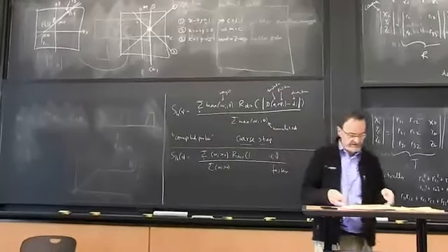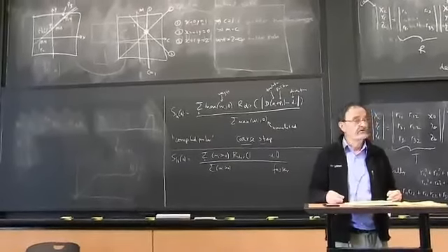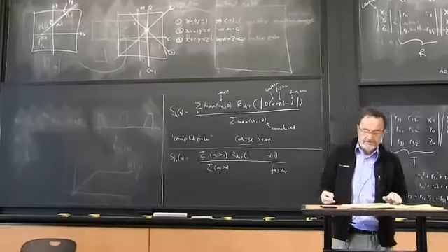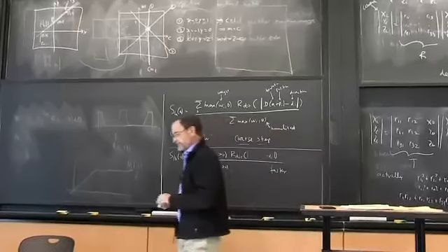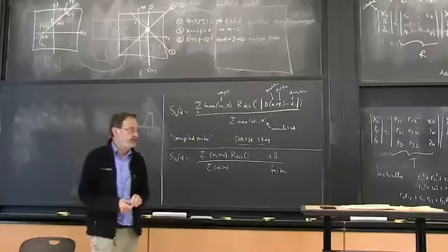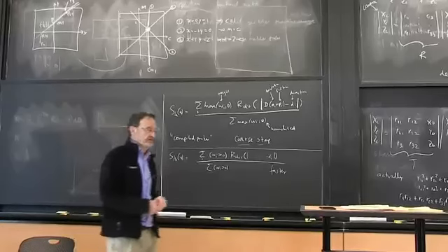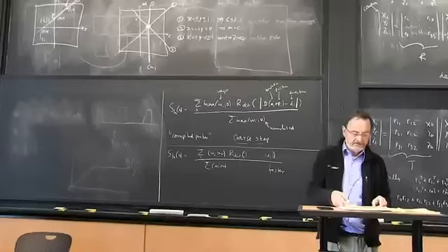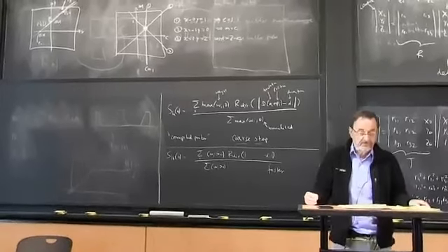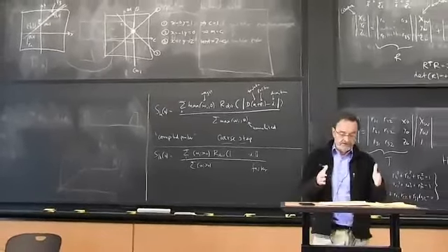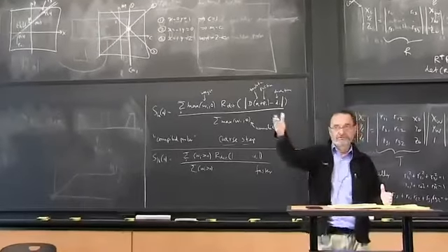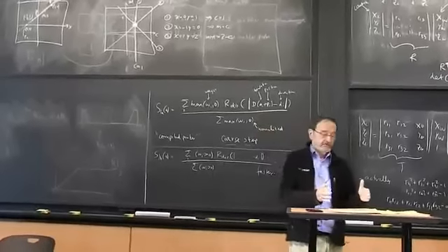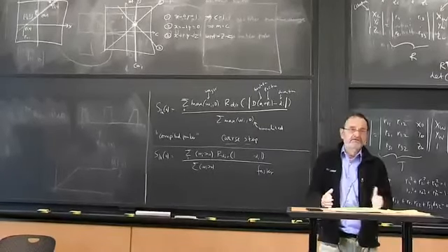In LTE, long-term evolution in cell phones, the signal from your cell phone arrives at a tower at a time after you sent it, of course, by an amount which depends on how far away you are. And LTE, unlike CDMA, uses time division multiplexing. So you get a slot to send your data, and somebody else gets a slot to send their data, and somebody else gets a slot to send their data. And if they don't fit in that slot, they're going to interfere with each other.